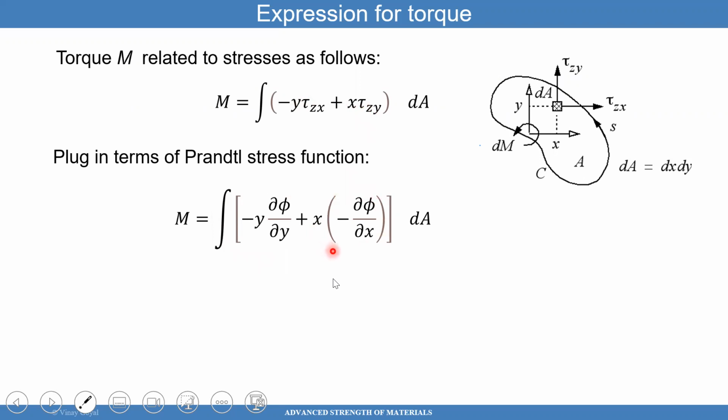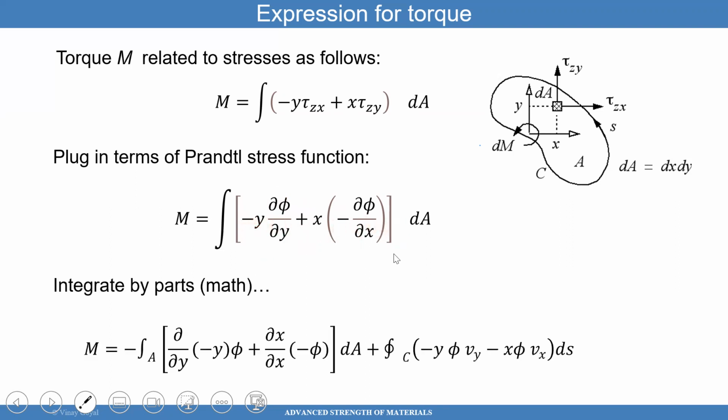Now, what you can do is a little trick that's done in a more advanced course, but you can actually do it yourself if you know calculus, and you can get dangerous with it. You can integrate these equations by parts. And when you integrate these equations by parts, after you do some math, you get this plus the boundary term that's a contour around the circumference. So around this body of material, I can do this integral. It's going to show up when I integrate this by parts.